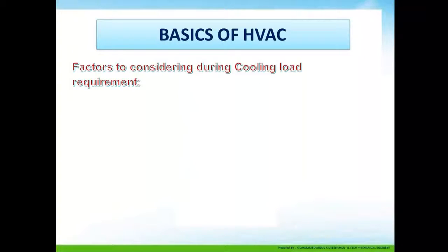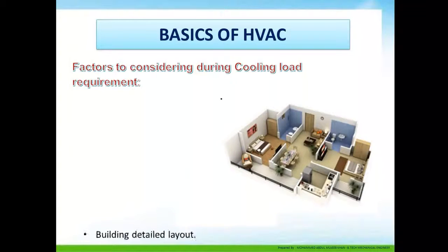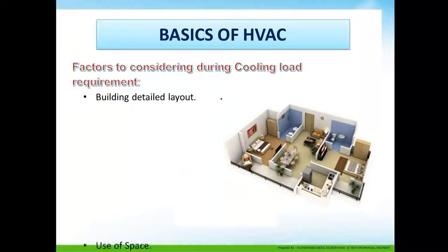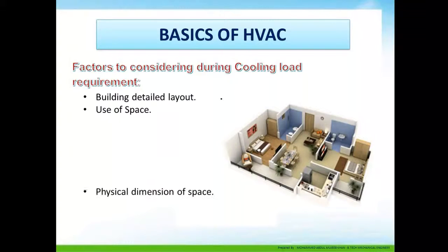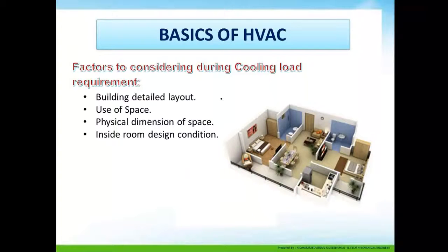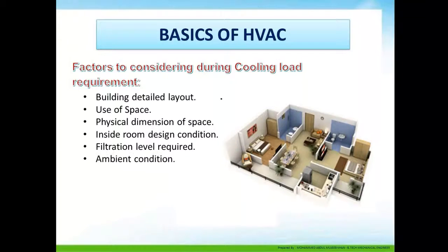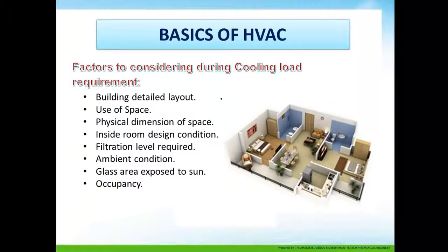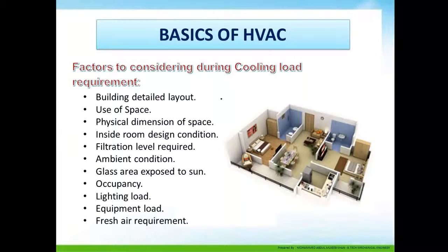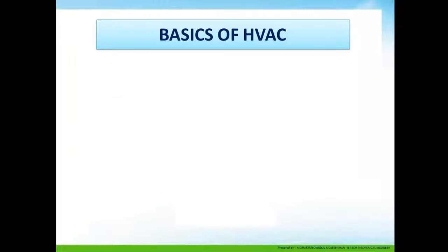Factors to consider during the cooling load requirement: building detail layout, use of the space, physical dimension of space, inside room design condition, filtration level, ambient condition, glass area exposed to sun, occupancy, lighting load, equipment load, fresh air requirement, and infiltration of outside air.